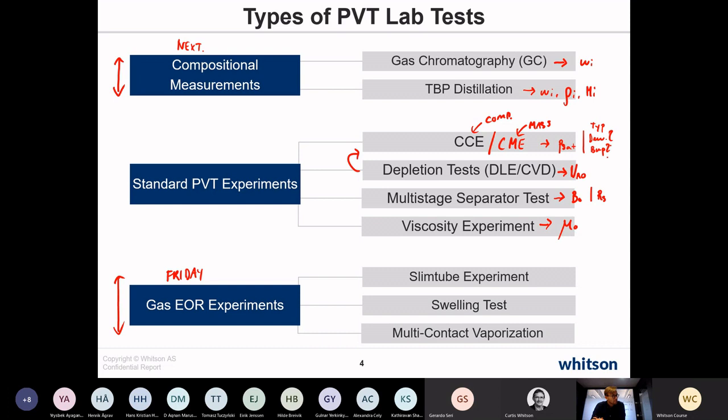Yeah, we recently worked on a PVT project where the fluid system was a highly near-critical gas condensate with a liquid dropout of about 60%. And there we had these measurements of the single-phase gas viscosities with this EMV tool. And that was okay. But the magnitude is usually very small, and you should expect more error with those measurements. So we have even seen it here recently. But mainly oil. And we'll get back to a few things on that.